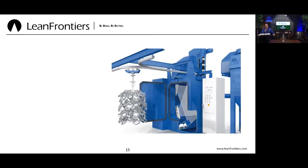Another one we had was the same thing, shot blasting. We did a lot of shot blasting. All our shot blasting, same thing with those die-cast machines, was done in batch. So you had a separate department that did shot blasting. You had to buy these more expensive machines. Again, a little bit of investigation, and lo and behold, they have these tabletop size shot blasters, which again, we could integrate right into the line and with one-piece flow.